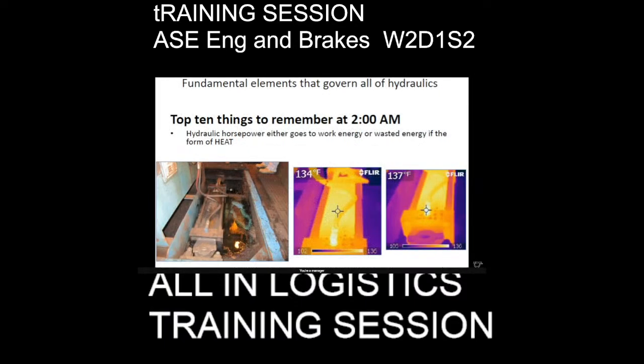What we want to prove with this is that hydraulic horsepower either goes to work or it goes to heat. For an example of that, there's a hydraulic cylinder over to the right. You see I'm measuring that 90 fitting right there, and it's 3 degrees hotter. So what that shows you is that when oil has to reduce down, there's a pressure drop.